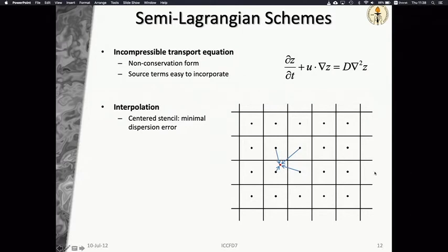The grid size is the distance between these cell points, right? I'm saying, to interpolate and find out what the phi of this blob is, should I use the surrounding 4 points, or should I use the surrounding 4 by 4, 16 points? The more the better. Exactly, the interpolation will be more accurate if you use more points, but it also increases the computational cost substantially.